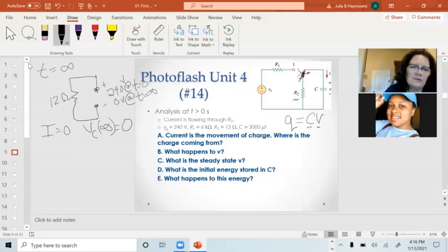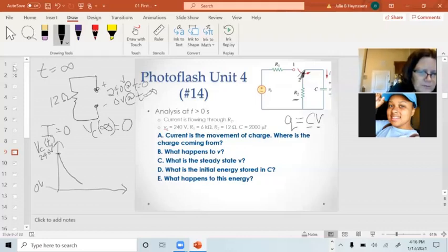So I initially have 240 volts. It's going to decay to 0 volts. And I'm just going to declare this. I'm not going to try to prove it at this point. You get a physicist to try to prove it to you. What's going to happen if I plot VC as a function of time? It starts out at 240. It's got to go to 0, and those are in volts. And it's going to decay exponentially. That's my best attempt at an exponential with this pen.